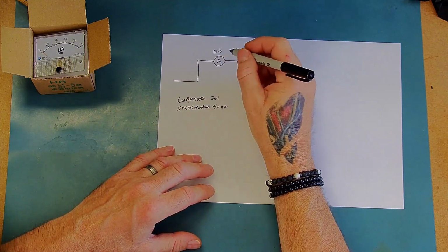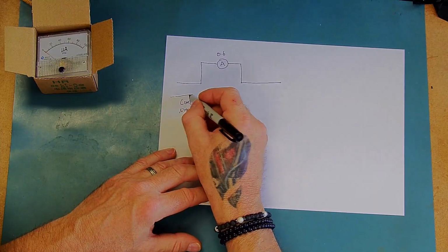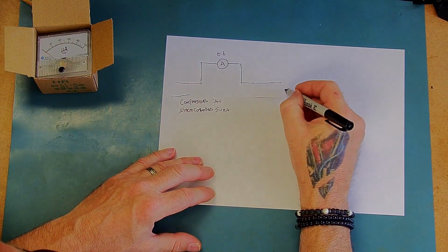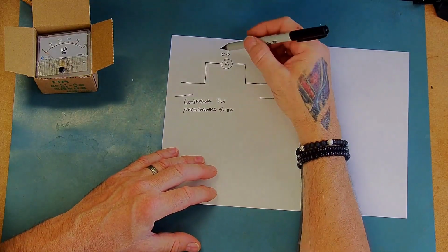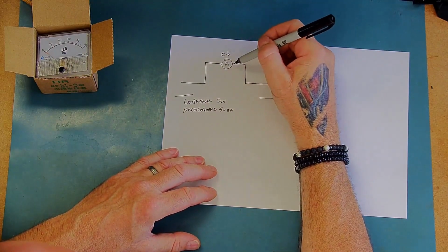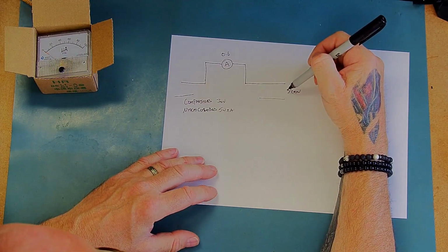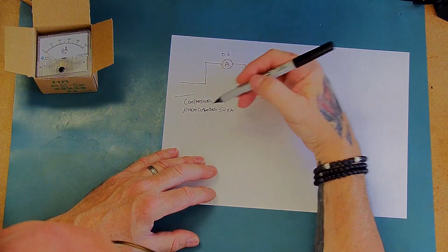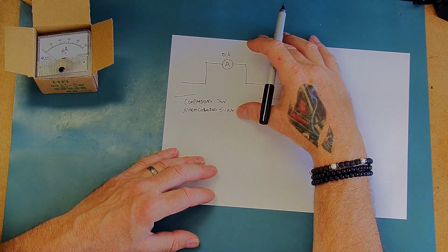But the actual device under test is going to have a potential here of, let's say 800 volts. Now although we're not actually going to have 800 volts across the meter, we are going to have an 800 volt potential, which we're going to need to measure, and we're going to be measuring at that potential.